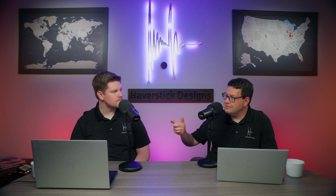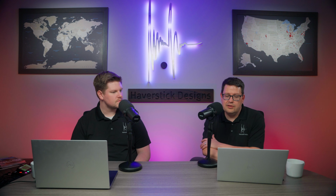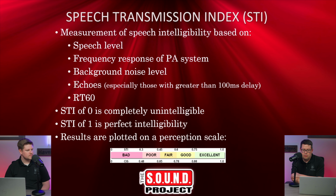But to get it to that excellent level, you'll see on this chart, 0 to 0.3 would be bad, 0.3 to 0.45 is poor, 0.45 to 0.6 is fair, and 0.6 to 0.75 is good. If we can get in this excellent range, which is 0.75 and above, that's what we shoot for, so that speech can be heard and understood clearly. Unless the client's wish is that speech is good but not perfect, so that the music doesn't suffer, and then we'll shoot for a little bit lower STI because we don't want the music quality to suffer any.